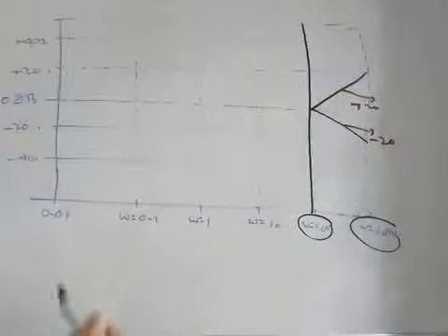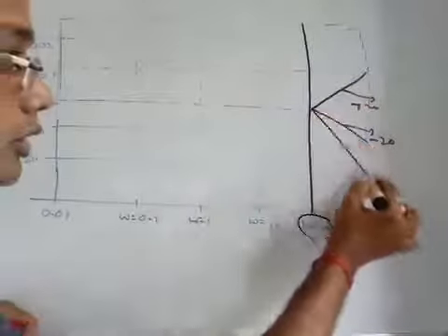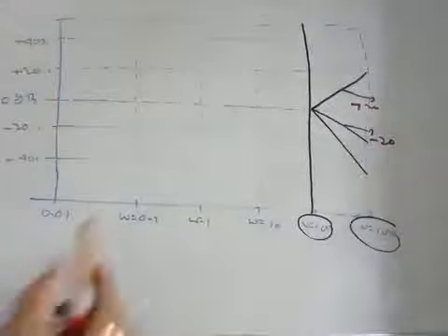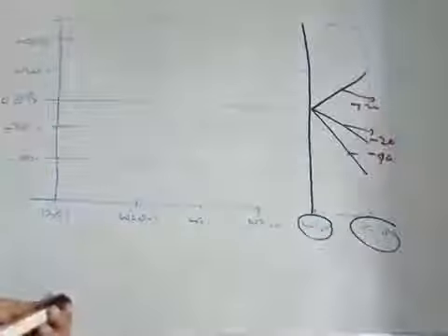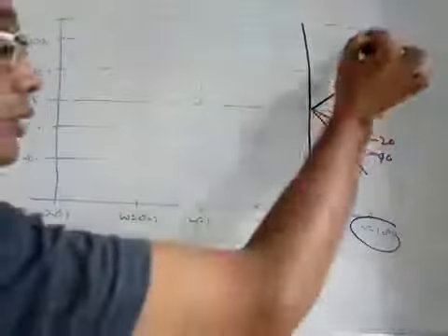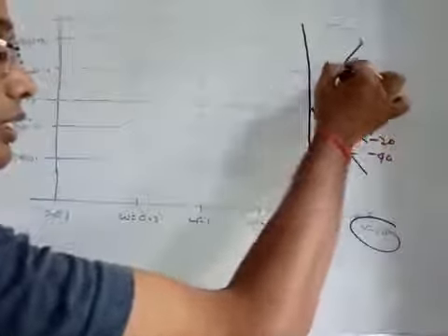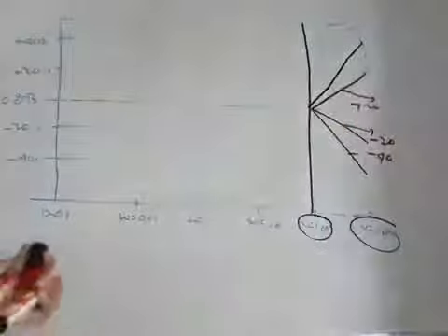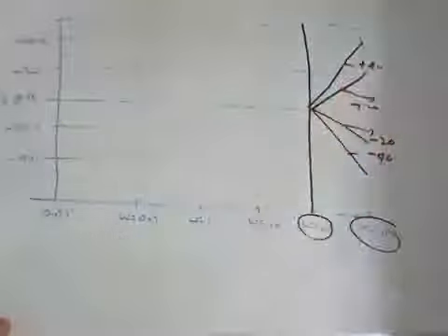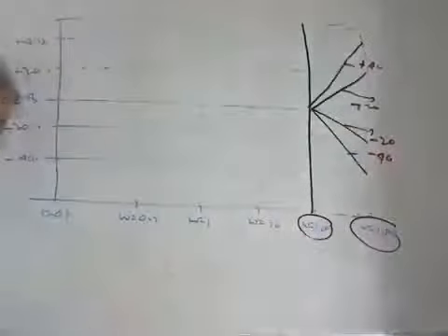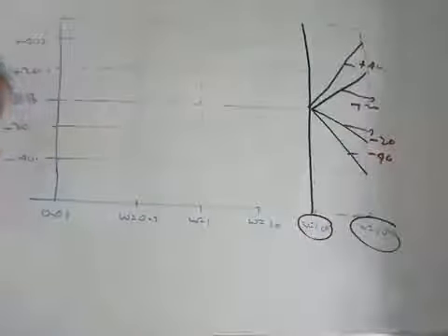Next you can draw this line, which means minus 40 dB line, and you can draw from 0 to plus 40. So this straight line has a slope of plus 40 dB per decade, right? So these are standard lines which you normally have to draw first.